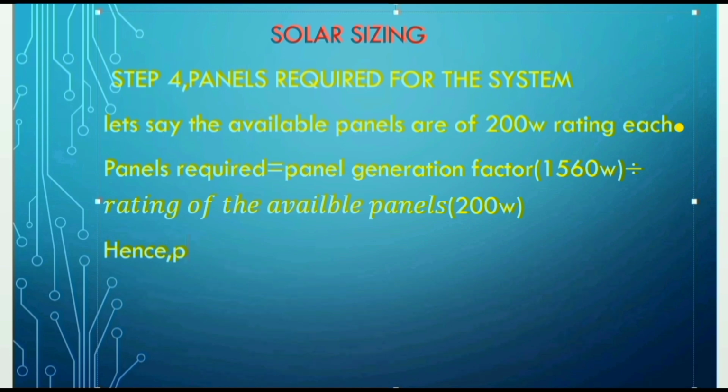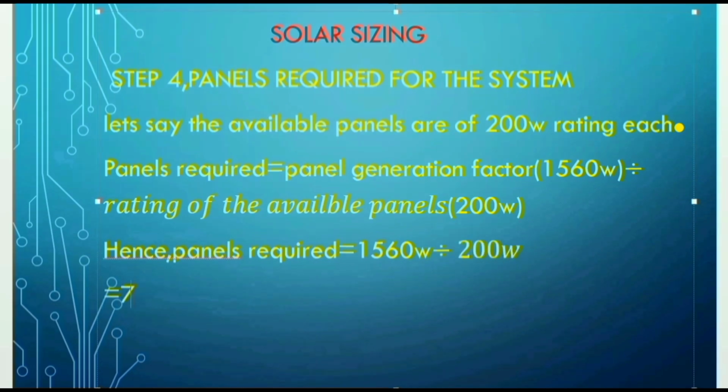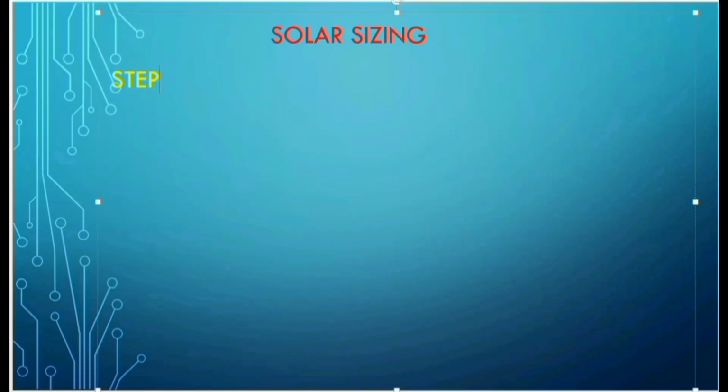Hence, panels required will be equal to 1560 watts divided by 200 watts. That is 7.8, that is approximately 8 panels. Approximately 8 panels will be required.